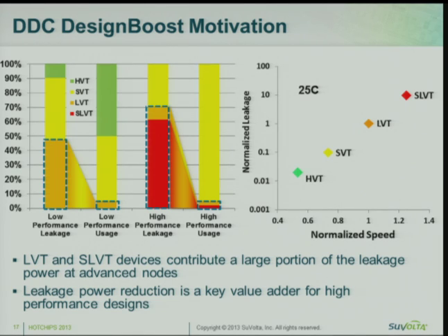If we look at higher performance devices like a CPU, here I'm using 95% SVT. I've allowed 2% super low VT, and that consumes 70% of the leakage. And in fact, it could be worse depending on the number of low VT transistors you use. And we've seen data from customers that says it really can be worse.